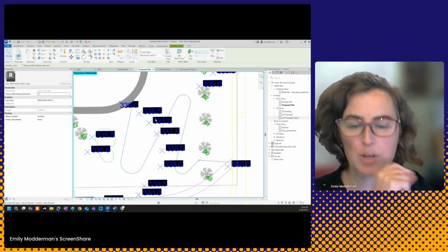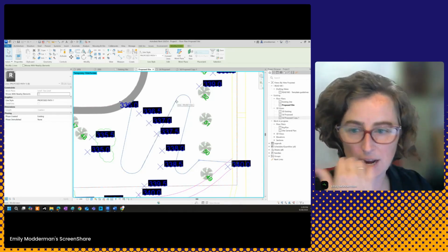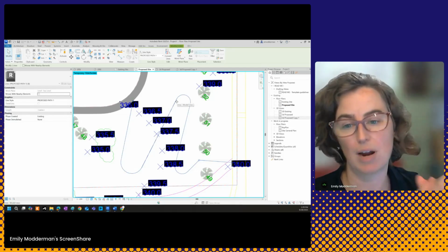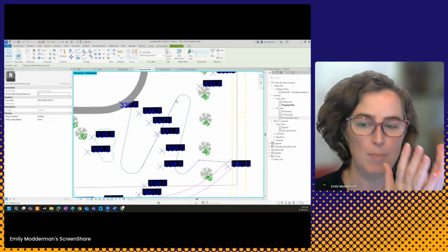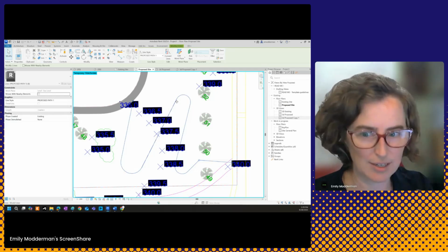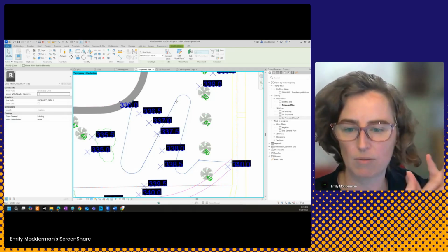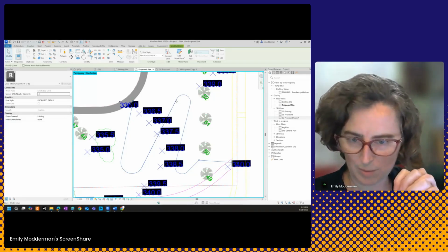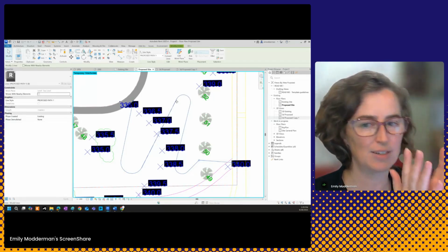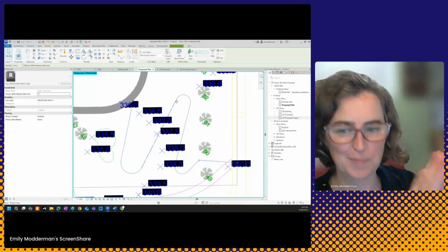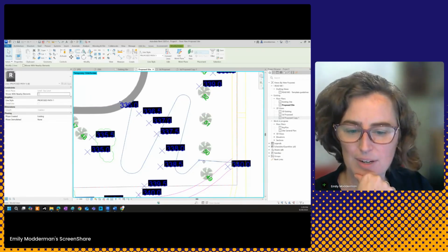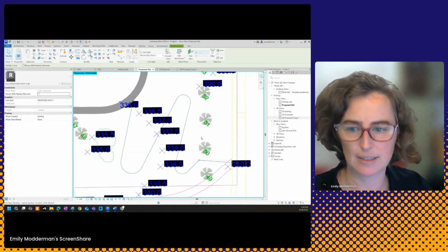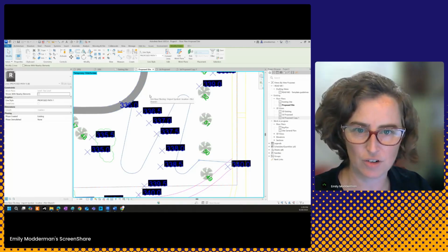However, before you get to that final path, it's a good idea to have an idea, okay, 340 to 336, I still need to know roughly how long I need to make that. I'm obviously going to be hoping for an accessible slope here, so we're talking in and around 4% or less. And there's always some pre-work to be done. Environment, Revit doesn't entirely do your job for you. So calculations have already been done. I know that I need a specific length of path based on my distance over slope calculations.